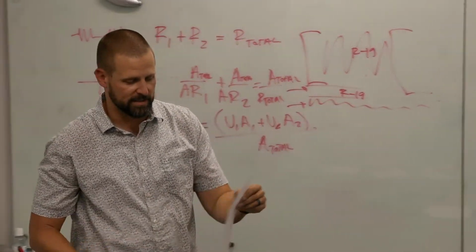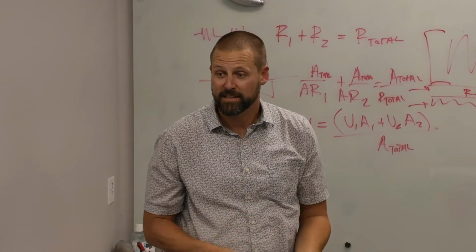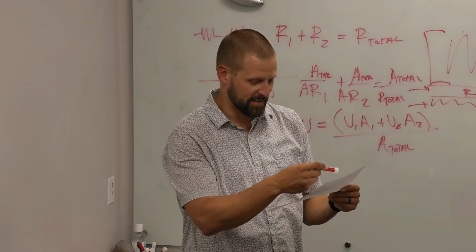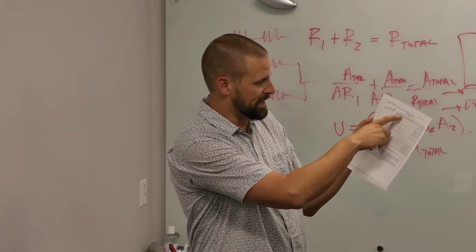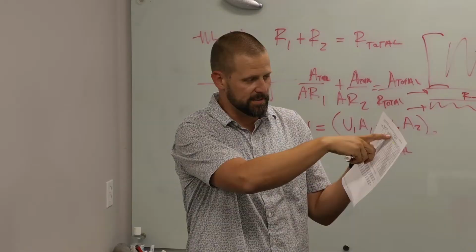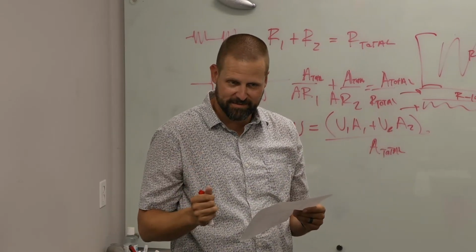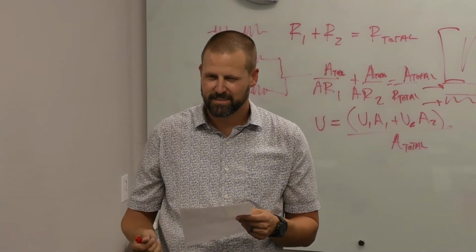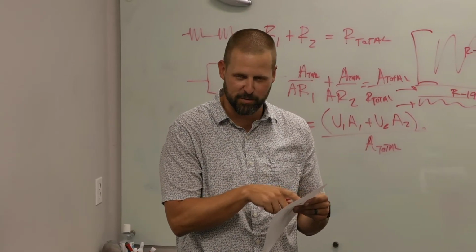So we're gonna be 1, 2. Oh, and what's nice is they set this up like Battleship. You've got 1 through 30 in the gray, and you've got A through K in the gray. You see how the rows have 1 through 30 and the columns are A through K? So like Battleship, I can say the answer is A4. You're not going to say hit or miss, you could read the U value, which is 0.217.